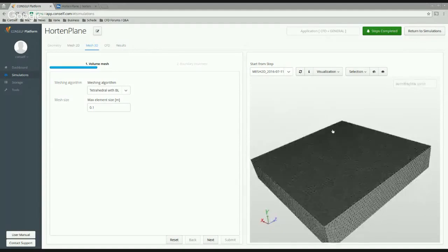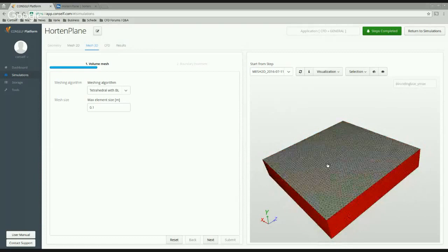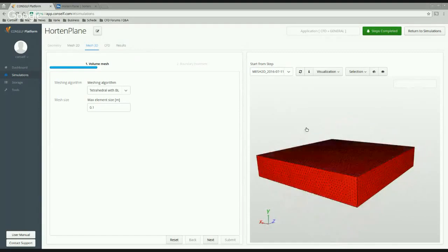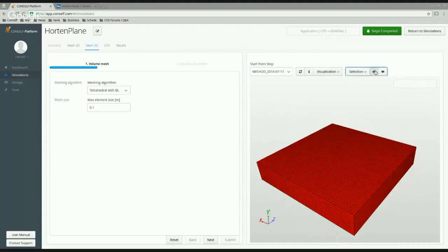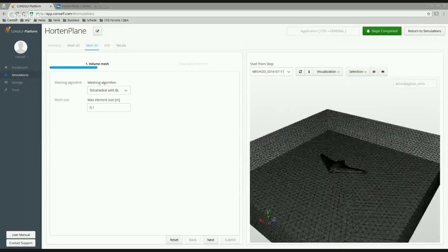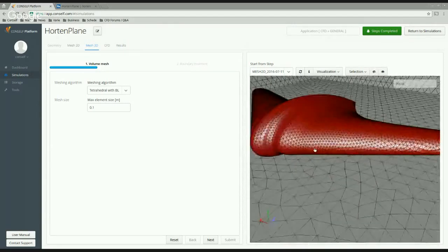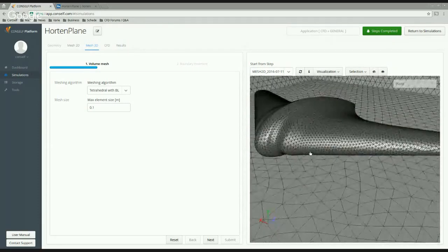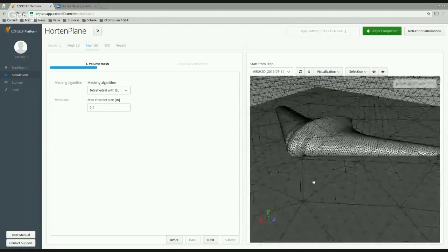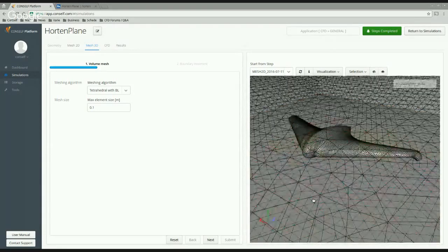Now we have our bounding box divided into small triangles. These triangles are around 2 meters wide, as prescribed, while the plane inside, as you will see, has much smaller triangles, around 25 centimeters. So, okay, this is the Mesh 2D result.